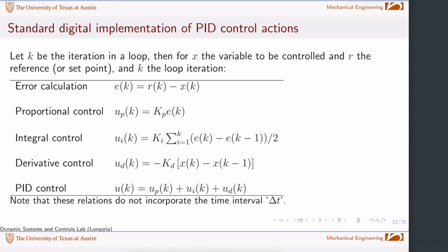I'll talk a little more about how you implement this in other ways. But because we are doing this on an Arduino, it's going to be a digital implementation. If you look in the textbook on digital control, there are some standard representations. A digital controller is an algorithm, it's code. You'll write it directly in C code on an Arduino, and you're just making calculations. So this error is now a line of code, with X as the process variable you're trying to control.